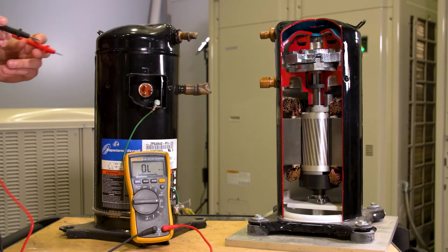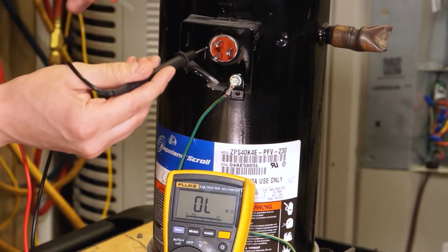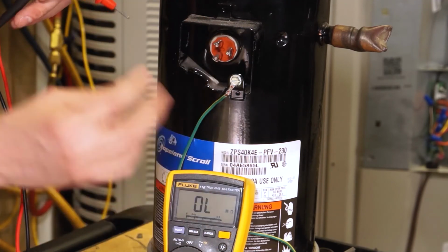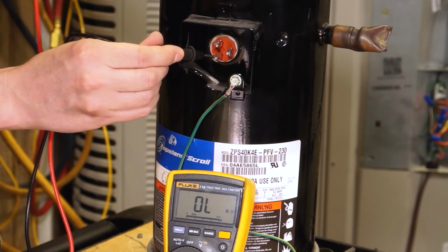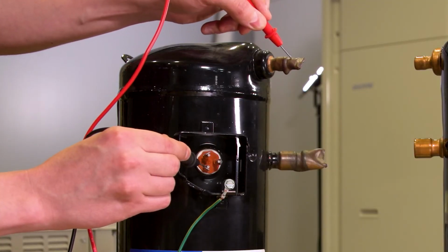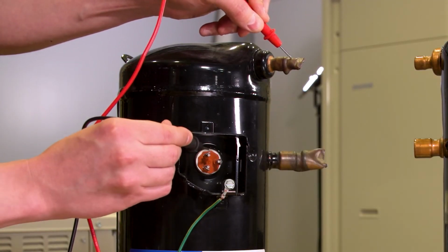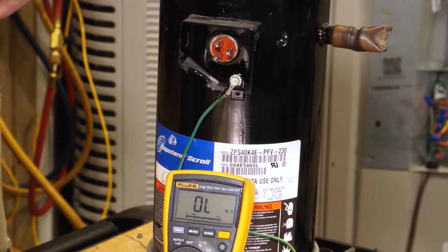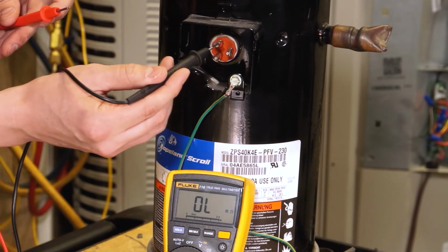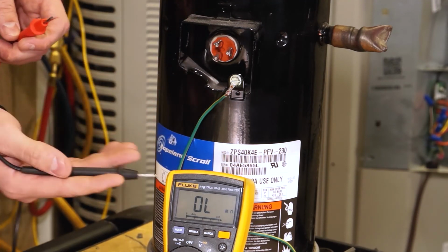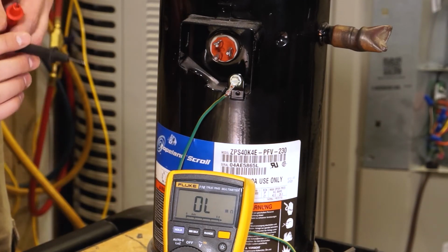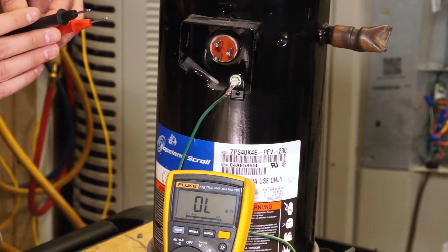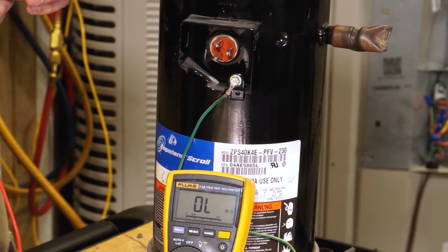Now, if you were ohming a compressor to ground, basically what you would do, and again, you want to do that directly on these pins, is pull the plug off the compressor and put one meter lead on each of the pins. The other meter lead can go just directly to copper as your ground, and then you'll go to each terminal to ground. What you want to see on your meter is OL when it comes to ohming these three pins out to ground. If you either read a number on your meter or 0, we've got a grounded compressor at that point. So when ohming those terminals out, that's what you want to read on a good compressor.